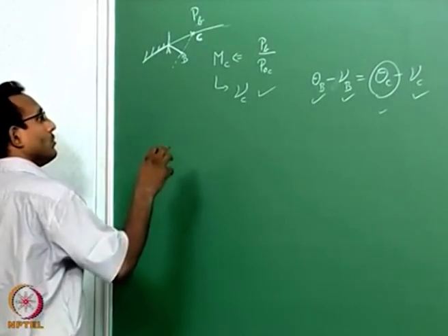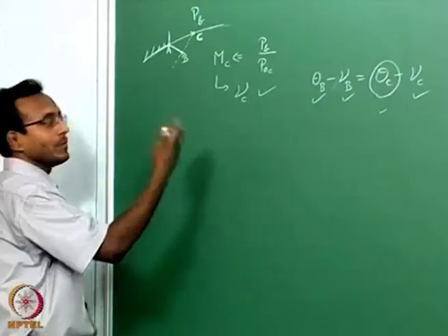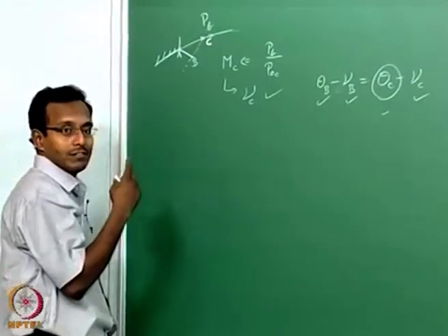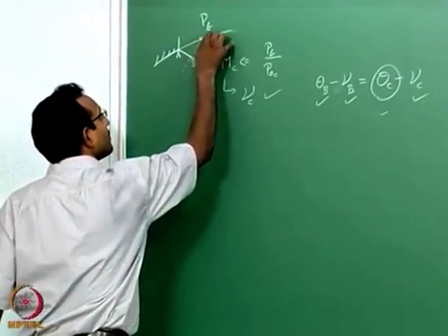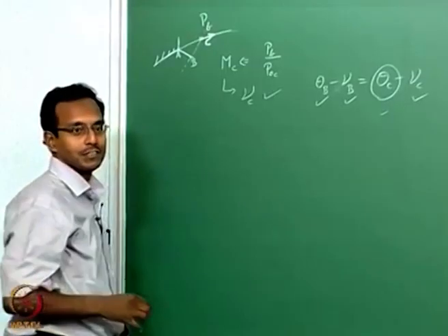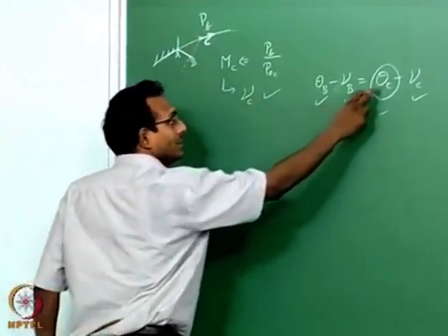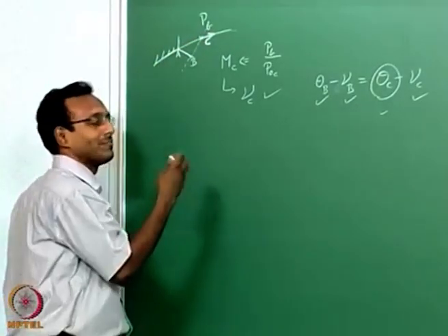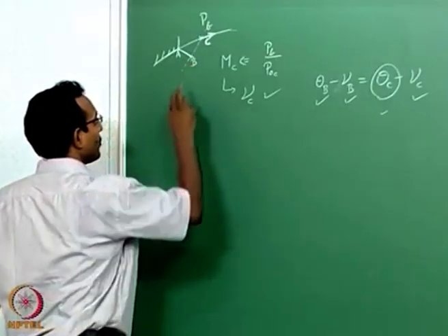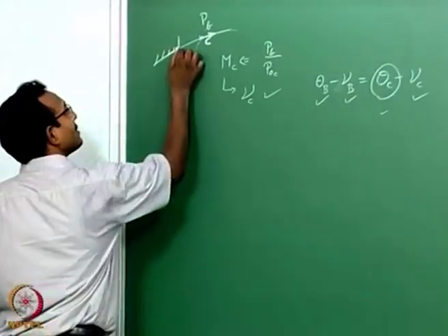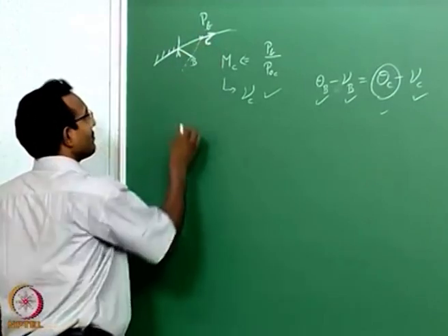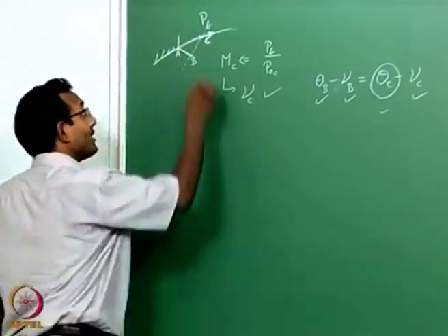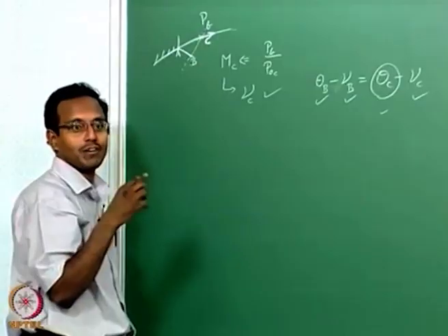Now after we have found this, the remaining thing is to find the velocity direction. We know that the jet boundary will be going with some velocity vector, some direction, and that will be equal to your velocity vector direction. So I know that at that location theta C is the angle of the velocity vector, that is found already, that is, tan of theta C will be my dy by dx at that location. But what I do not know is what this curve here is. If I do not know the curve, I cannot find the BC line intersecting with this curve AC. So now I have to find the point C, as in the location xy of point C.